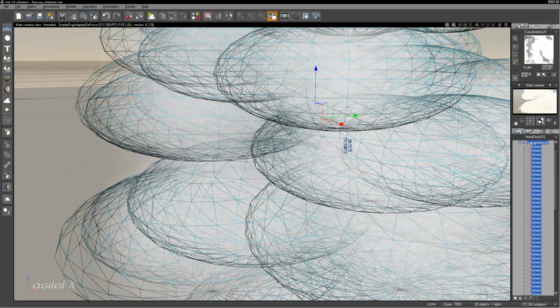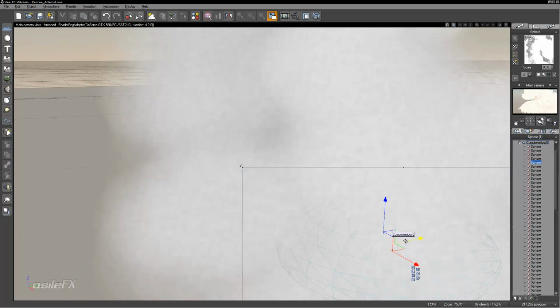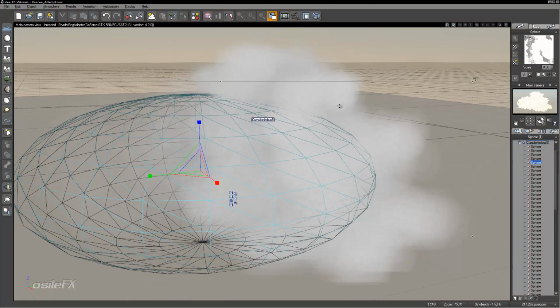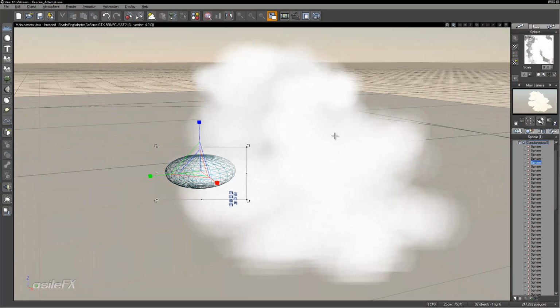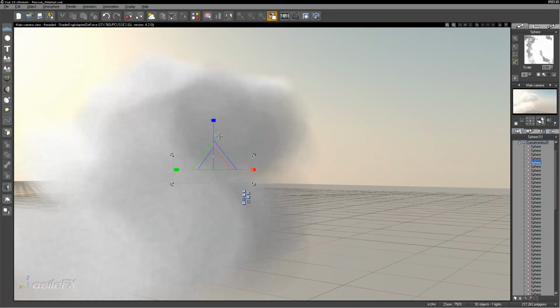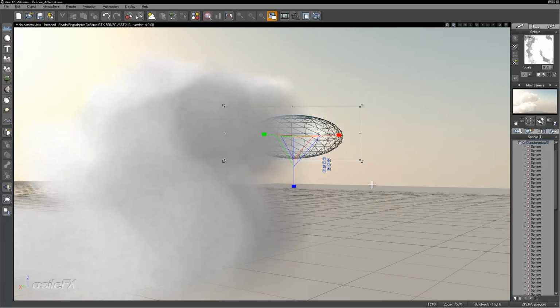Now to edit the cloud, if we take a look and expand the cumulonimbus group, we have a lot of spheres, and these spheres are what make up the cloud. So we can manipulate and modify, position the spheres where we want them in order to customize the cloud. If you want to add additional spheres, now that I'm within the cloud and have one of the spheres selected within the group, the cloud icon has changed to the icon for Add Metacloud Primitive. So we can click that option to add a new primitive, a new sphere within the cloud.